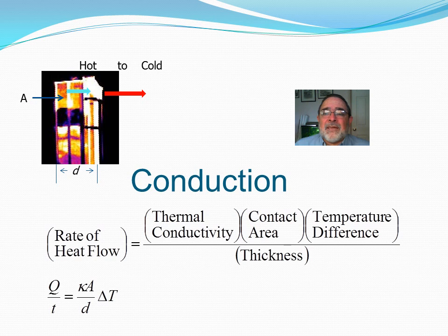Okay, and so you multiply that by the difference in the temperature in Celsius and divide by the thickness of the mass itself to understand the conductivity of this. You can get fairly complex in thermography, but it's not always necessary. But when you're presented with a complex picture, you need to understand where that energy is coming from, how it conducts, how it convects, and how it radiates, and from one into another. Let me show you what I mean.